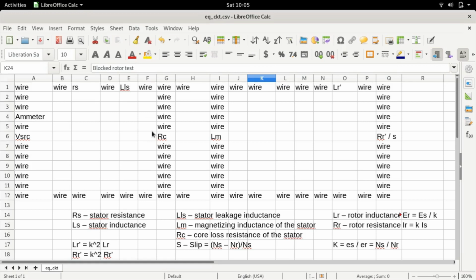In order to simulate a system, you need the dynamical equations of the system. And since we now have all these parameters, we can write equations for the flux linkages in the stator and also the rotor, and also calculate things like torque and therefore the speed. We will have to make assumptions of course, for the inertia of the rotor and also the inertia of any load that is connected to the system. But these details will come very soon. So in the next lecture, we are going to use this equivalent circuit, and we are going to start writing Python code such that we can simulate an induction motor using this equivalent circuit, right? That's what we're going to do.